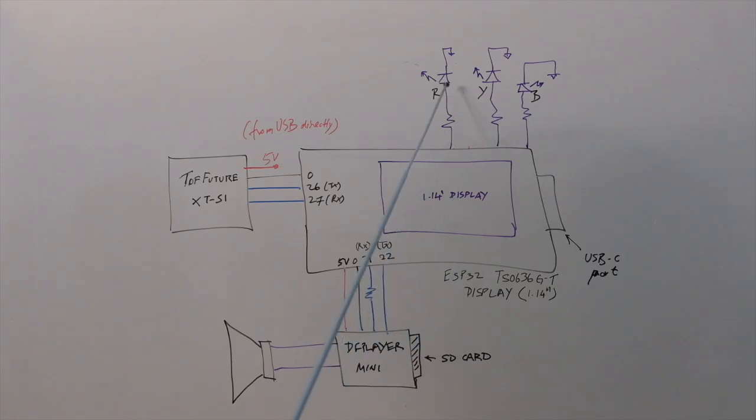And then there are the 3 LEDs over here, which are driven by 3 ports, which are just general purpose IO ports. I think I used 25, 32 and 30 on this one. I should probably write that down. And the other ports over here are used for the UART communications.